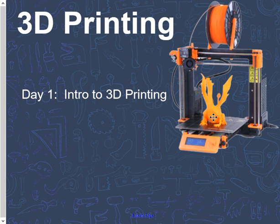So we put down one layer, so if you look at this dragon, that would be the tips of its fingernails probably, and maybe the outline of its belly back there. And then the x-axis picks up like 2 millimeters, very small amount. And it puts another layer on top of the layer it just created, and it just keeps doing that. So the extruder goes back and forth, the print bed goes front to back, and then after it lays down a layer, the entire x-axis moves up a little and continues printing.